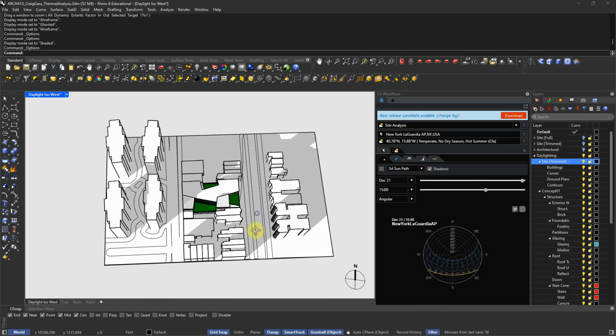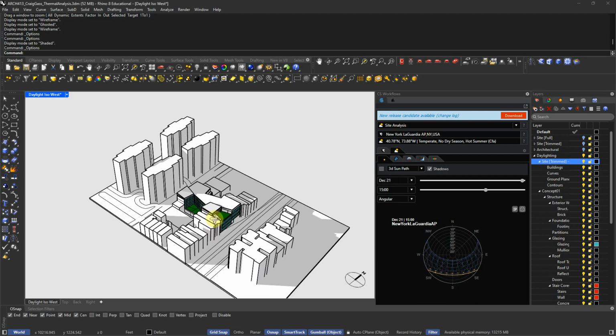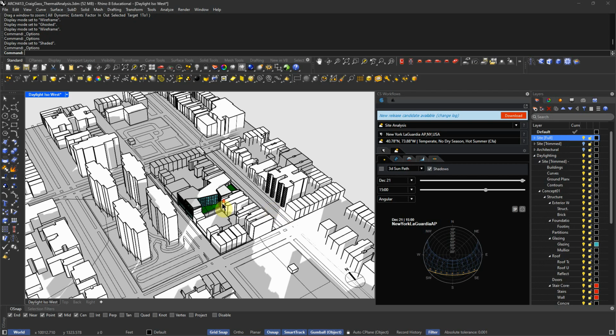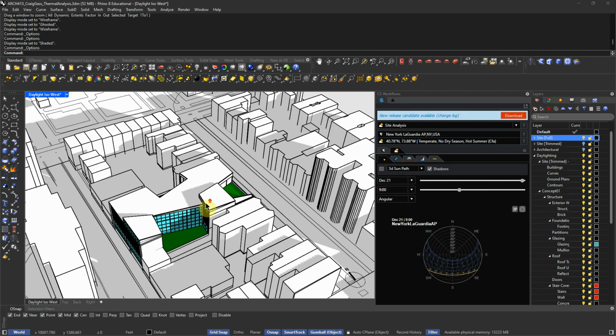The one other thing to talk about in terms of this is that this is great for daylighting in terms of defining what buildings are shading our site. What I often see is that people come way out here and do a shading study, and you're changing these times and the shadows are changing, but we can't tell what's going on in the actual site.